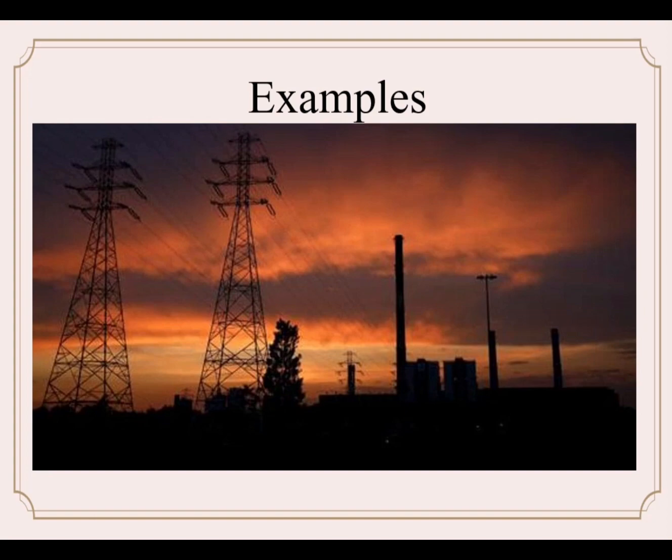This is because AC means transmitting the generated electricity over long distances at a high voltage, such as over 110 kV. Less energy is lost in electrical power transmission. Higher voltage means lower current, and lower current means less heat generated in the power line due to resistance. AC can be converted from high voltage easily using transformers.